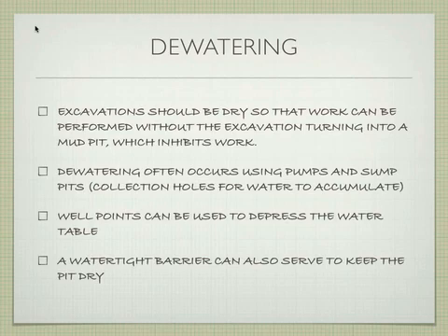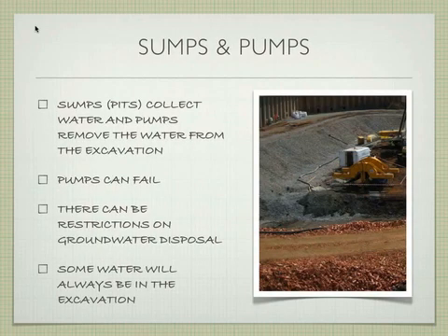Now recognize if you're excavating the bottom of the site and there's a high water table, the water is going to come up from the bottom. So this isn't going to solve the issue, but it gets you somewhere. Okay, so here's our sump pit, to collect and move water from the excavation. Here's our little pit. There's a pump in here that's going to pump the water out.